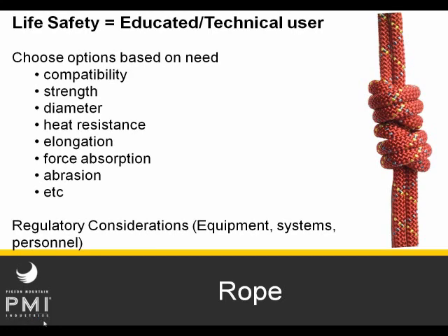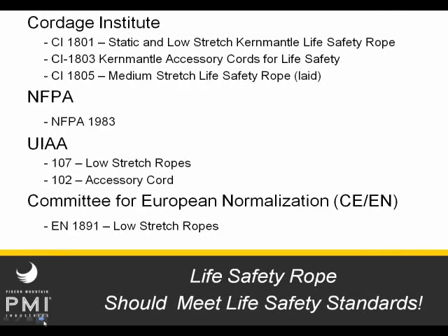That comes first. There are many different kinds of standards. We're going to start with test methods, which you see the first list here. The Cordage Institute standards listed there are all test methods. They tell exactly how a rope's to be tested. They tell how it's to be terminated at each end for the testing, what kind of conditioning must occur prior to the testing, how fast it must be pulled, things like that.